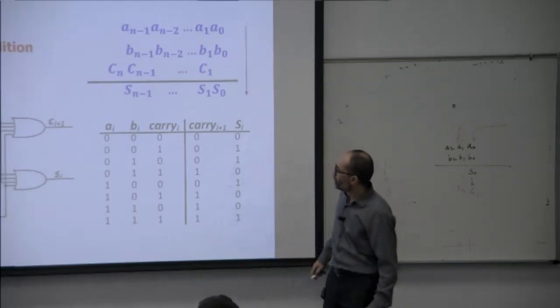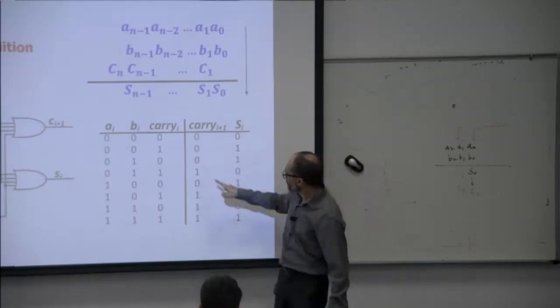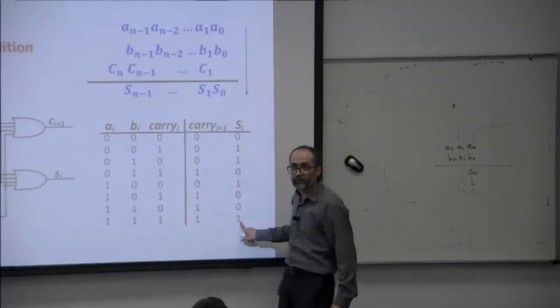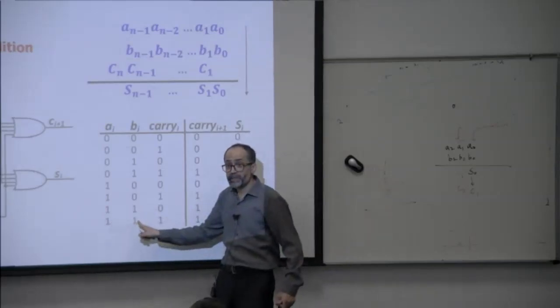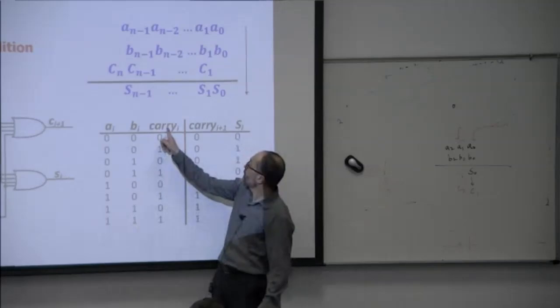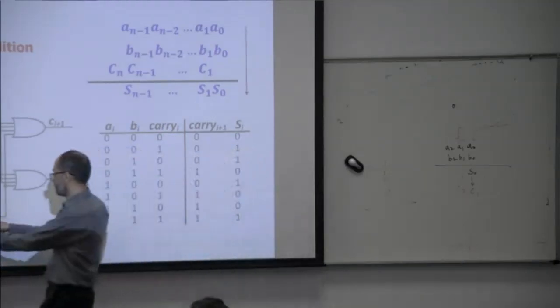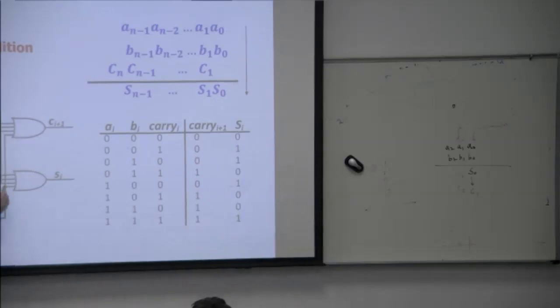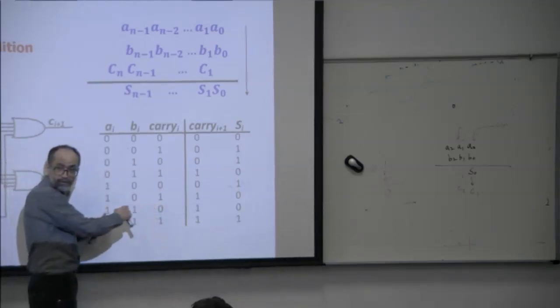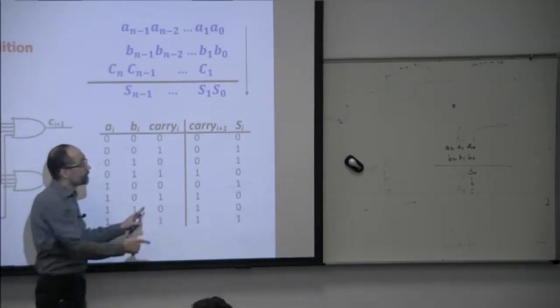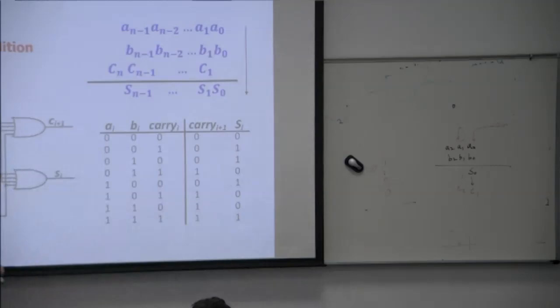Now if you look at here, for this expression 1 and 1, what is this? A, B, C. I'm calling it carry i. This A, B, C goes here and here. It's called logic sharing. Got it? Now look at the other expression, 1, 1, 0. A, B, C bar. A, B, C bar goes to carry. Where does A, B, C bar go? Carry or S? Carry.